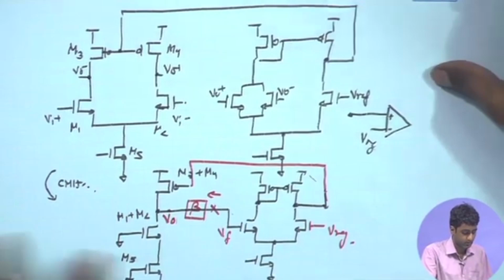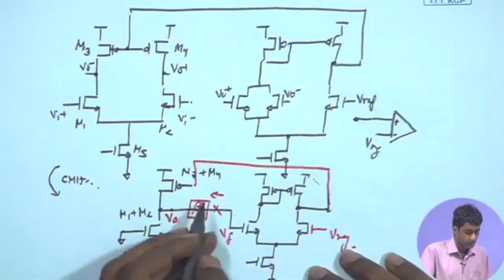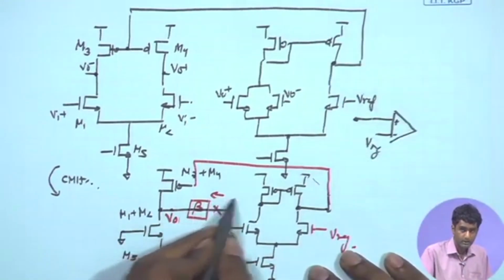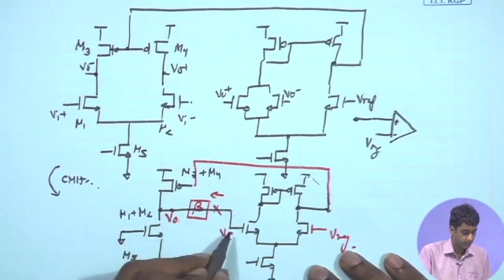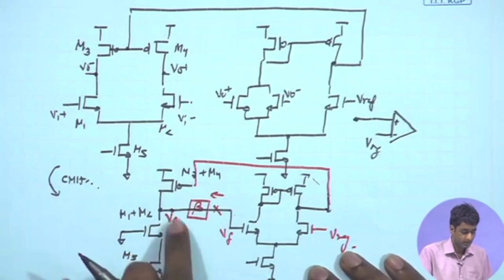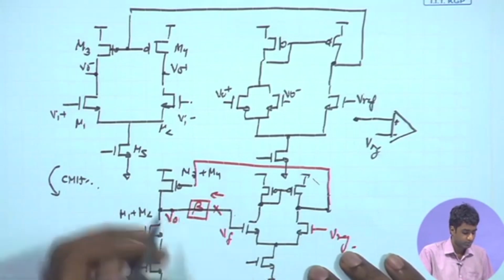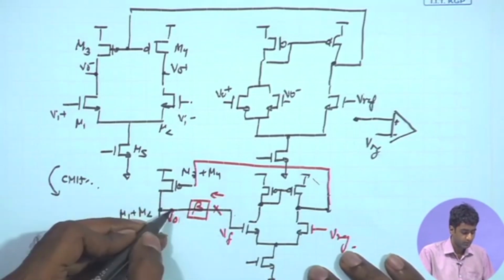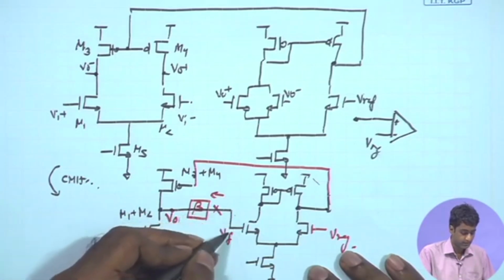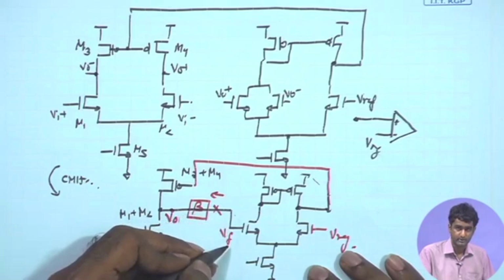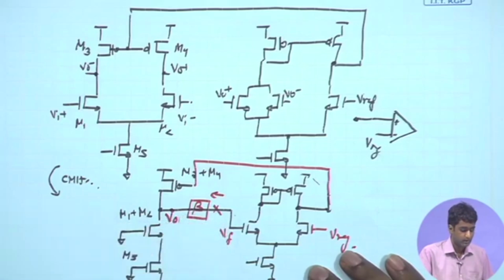So, let us draw the open loop configuration. Looking from the output port of the feedback network, the other terminal is shunt, and therefore, as per our earlier discussions on feedback topologies, in order to open the loop, the shunt terminal will be grounded, and therefore, you just have an AC ground established at this point while opening the loop.